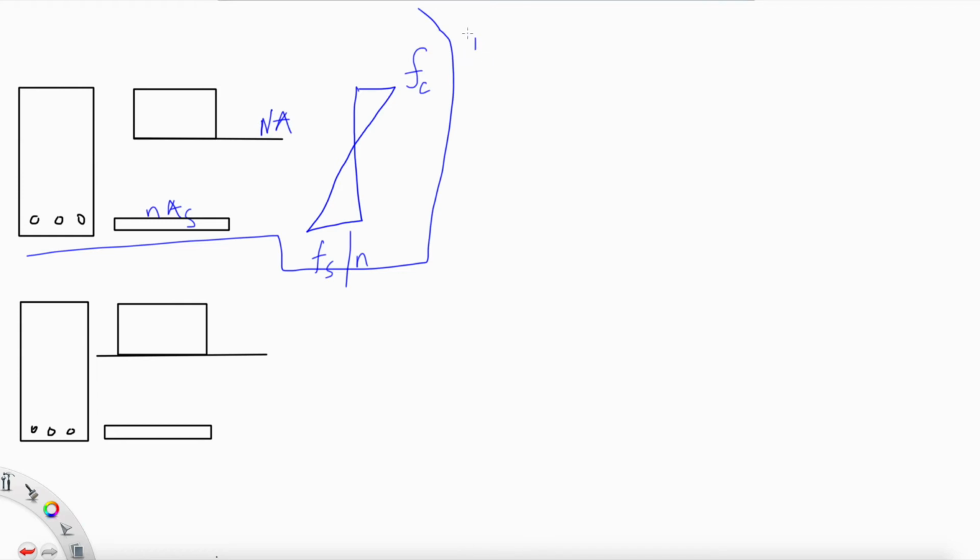First step to compute the stresses is we have to determine where is the neutral axis of the object. I mean by calculate neutral axis because the neutral axis moves up. It's not always in the middle. Because of the cracks and the tension, it can move up and keep moving up. Because what does it mean moving up? That means the concrete section is crushing and the stresses are taken by the steel.